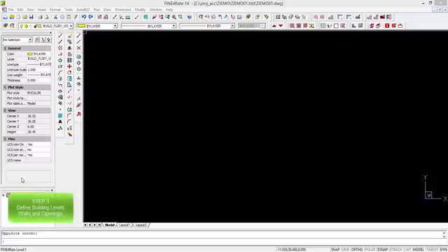Step 3. Define the building levels and draw the building shell in terms of walls and openings. I have two options. First, I could have the IFC 3D model of the building from the architect, which saves time and effort, or I could have the 2D plan drawings that I'm going to use as xrefs. Either way, I have to copy the architect's files to my working folder.